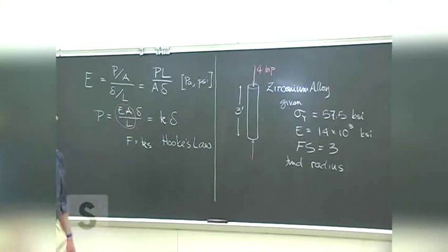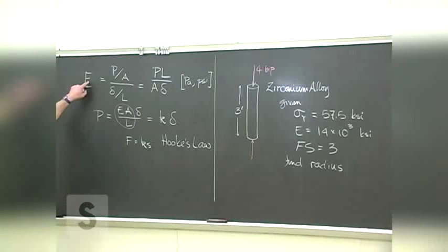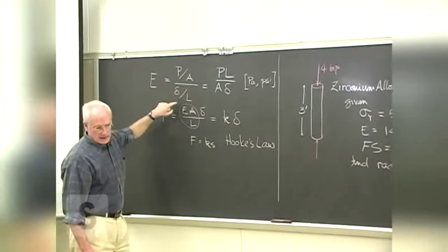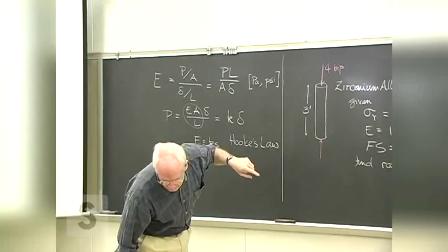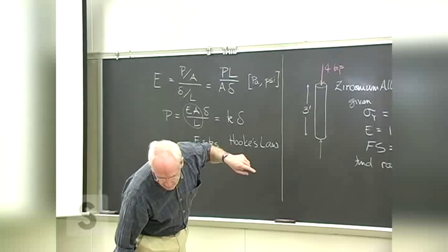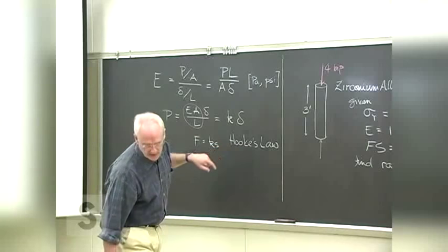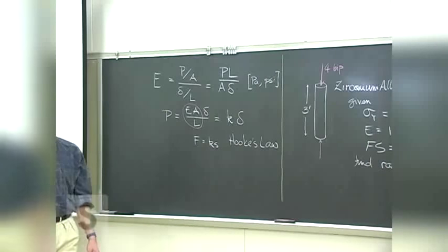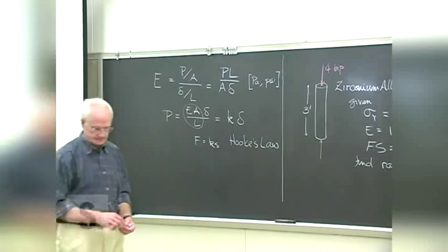Yep. All right, so given the modulus of elasticity, given the load, yeah, we've got all the parts we need. We can then find the area, and then from the area find the radius.